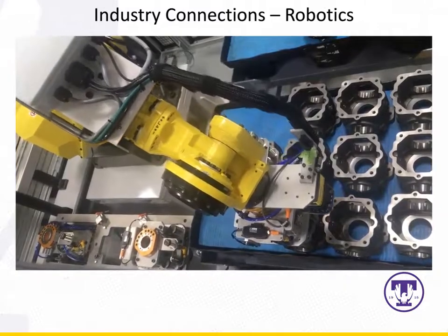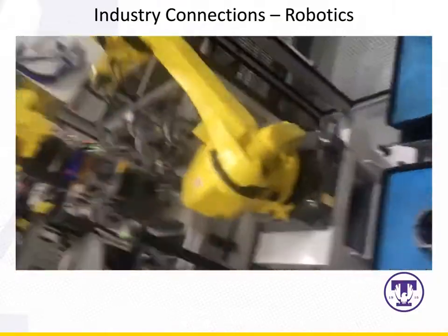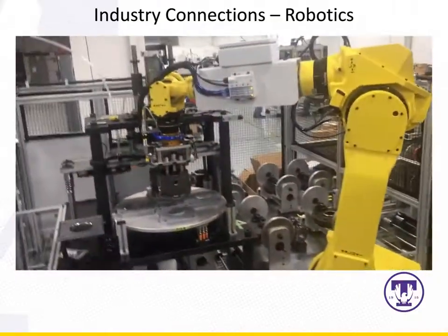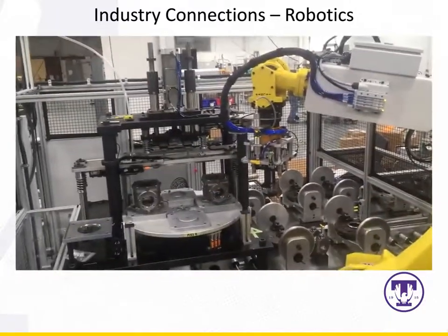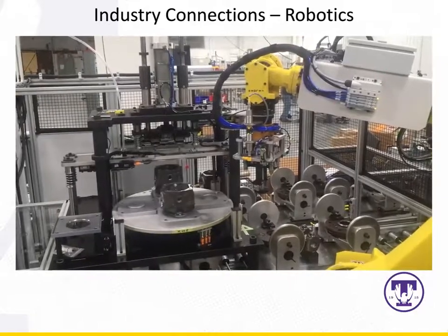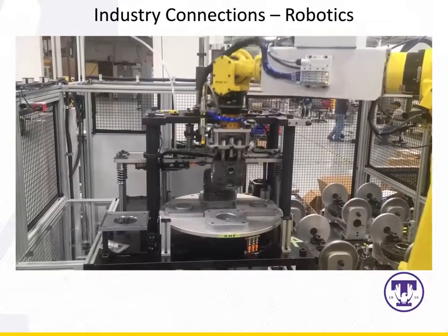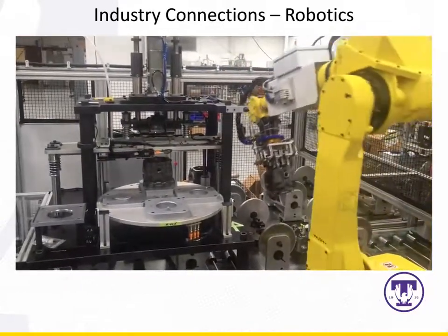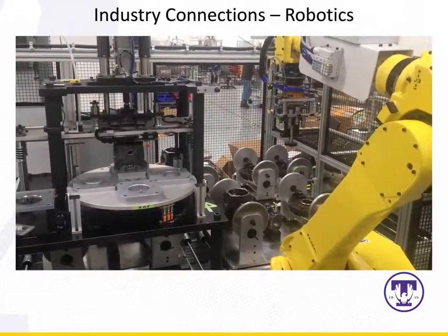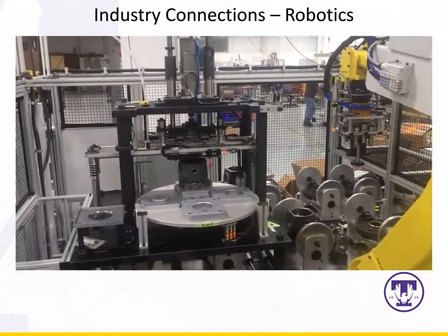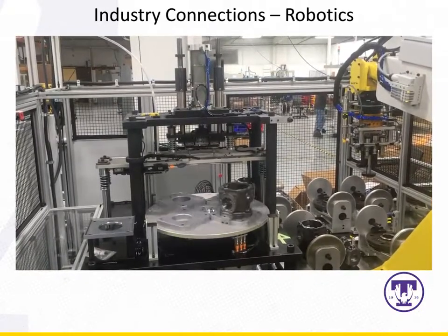So here we're seeing the robot being driven by a camera. We have vision being used in industrial situations. We have a robot being used to provide complex motion, and we see that it's still fundamentally making use of this pneumatic control. And then it's waiting for a process to finish, and when this comes around, this component will also be loaded to this pallet.